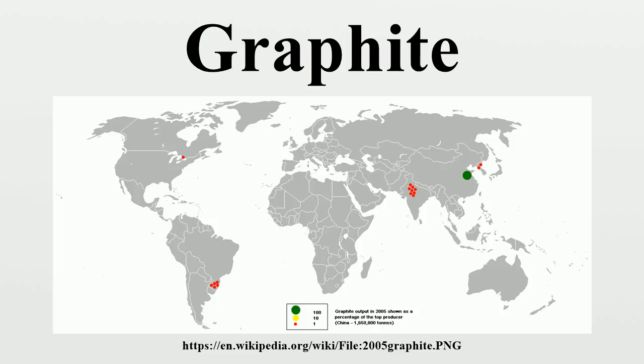The use of graphite is limited by its tendency to facilitate pitting corrosion in some stainless steel, and to promote galvanic corrosion between dissimilar metals. It is also corrosive to aluminium in the presence of moisture. For this reason, the U.S. Air Force banned its use as a lubricant in aluminium aircraft, and discouraged its use in aluminium-containing automatic weapons.